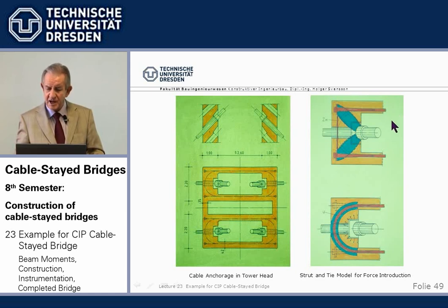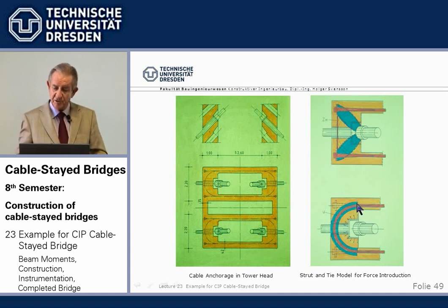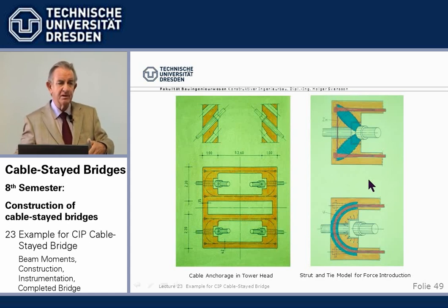One half of the cable force goes in direct compression struts into the end anchorages, and the other half of the cable force is taken by the radial forces from the loop curvature at both ends. And that's the way we take up the cable force.